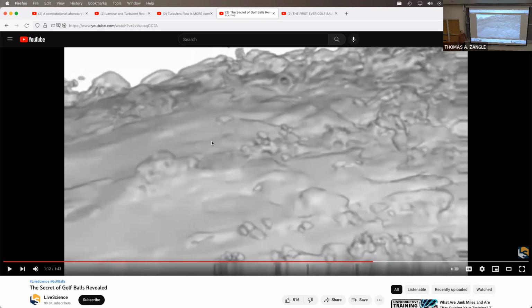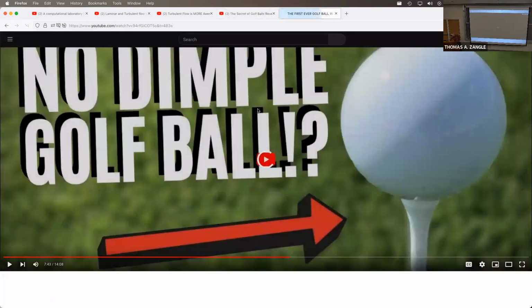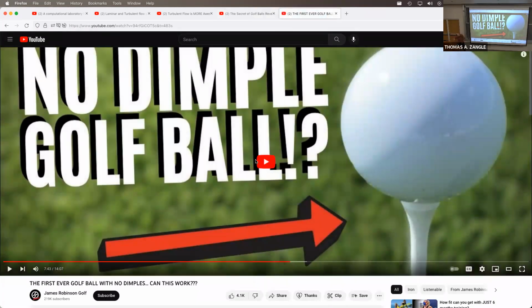So the turbulent boundary layer has more efficient mixing. It pulls in the momentum of that free stream air, which causes a decrease in pressure drag. All right, so last one, it's just going to be what would happen if you actually try this? If you went back to a perfectly smooth golf ball, what would actually happen? And so this is a video showing exactly that.